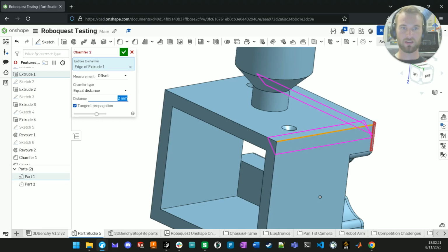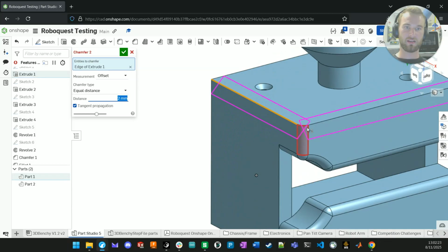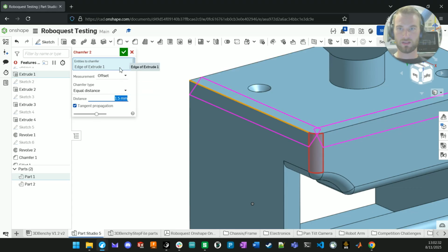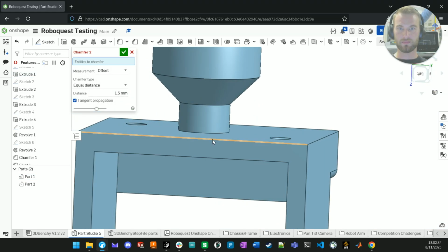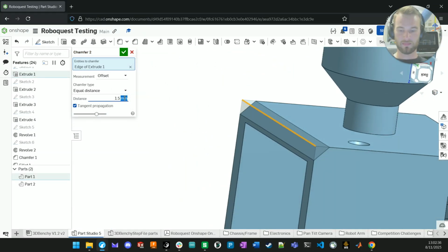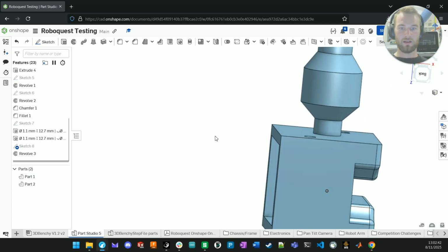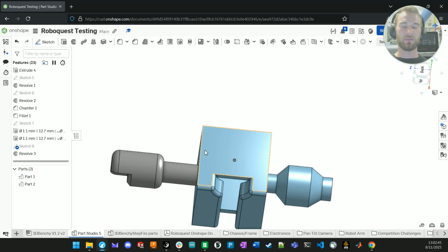So yeah, 2 millimeters is larger. It starts to get problems with calculating your fillets. So let's just say 1.5, or we can just select a different one. So they go 3. See how it gets larger. All very useful tools. You're going to be using extrudes, revolves, and fillets and chamfers a whole lot.